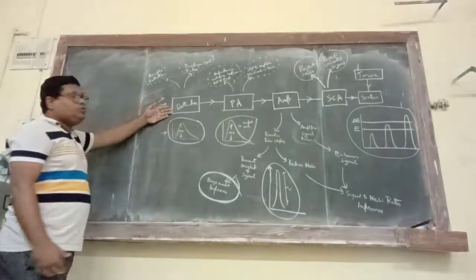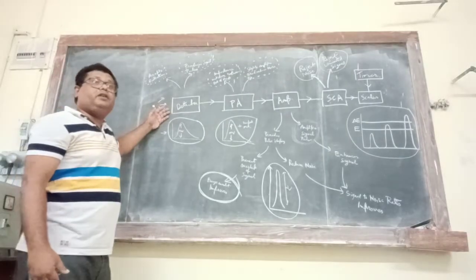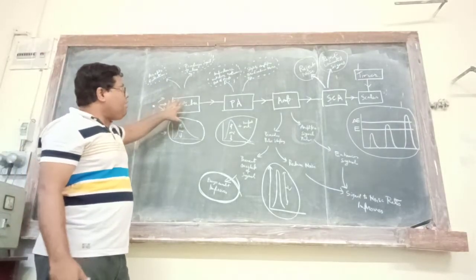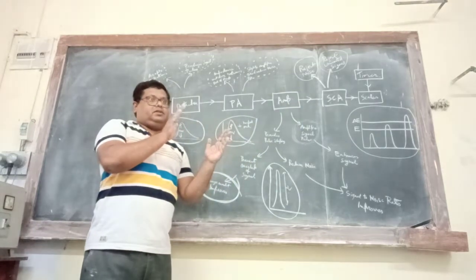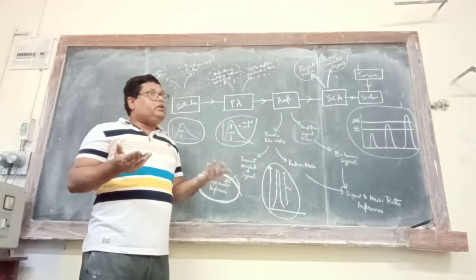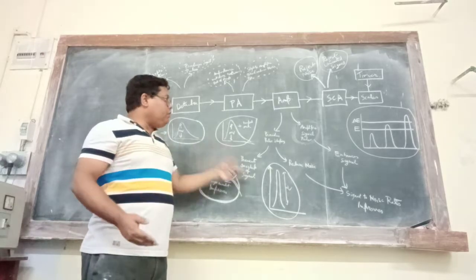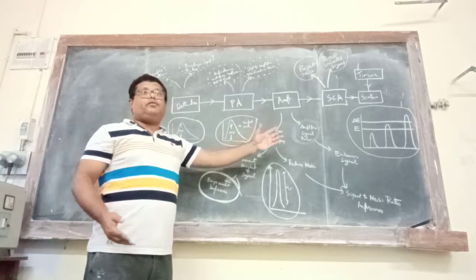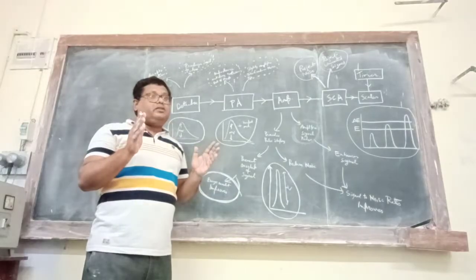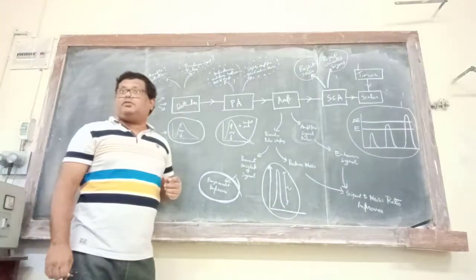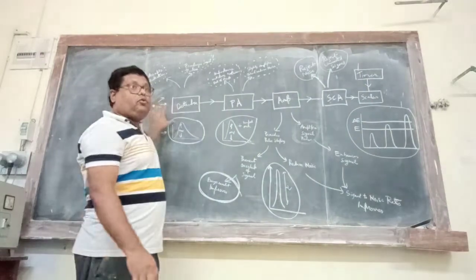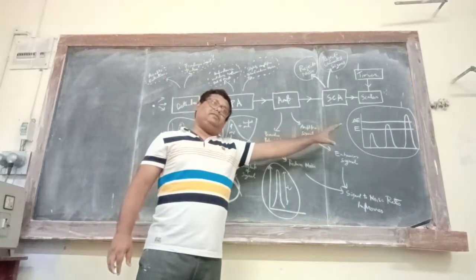So even if you choose a detector which has very good energy resolution, if you have not so good components, then the pulse width will be very large, and what will you observe? You will observe the overall effect. So the overall effect will be a very bad energy resolution, even though your detector has good energy resolution. Understand? So we have to keep all these things in mind.